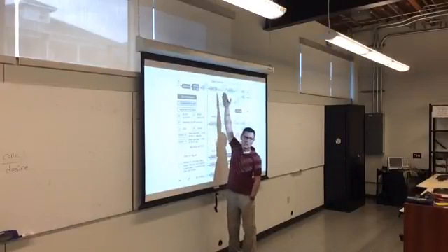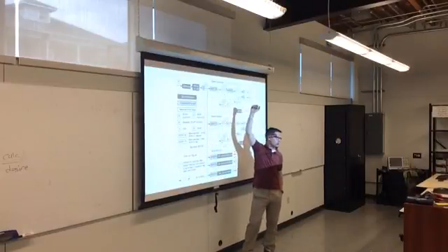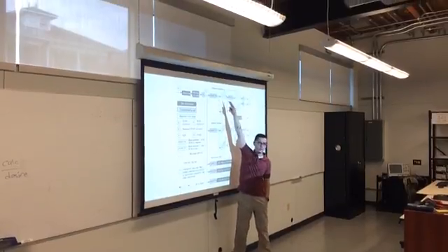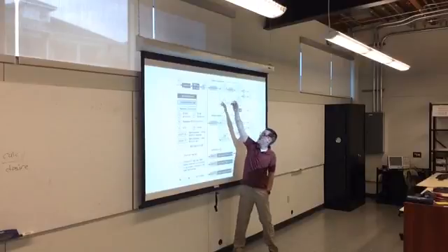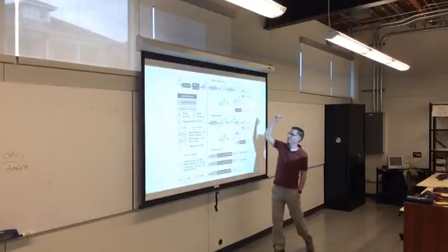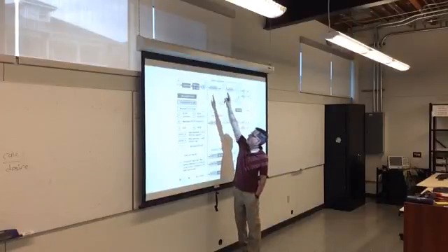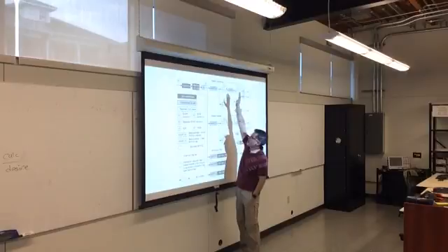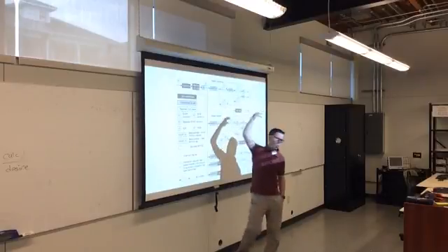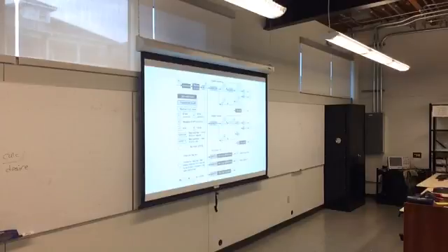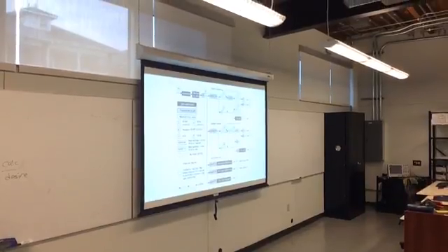So these lines here generally mean waits or events that you have to respond to. So you send a start, you send an address packet with a write, you wait for the slave to acknowledge. The white boxes, the empty boxes, are things that the slave device will do. Once you receive that acknowledge, your device moves into a different state and you can send data.